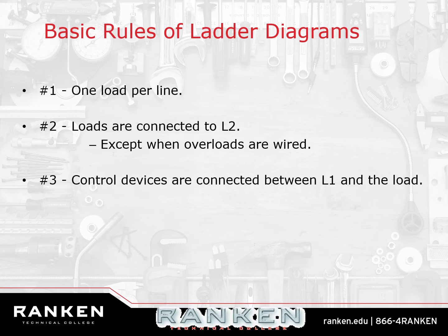Number 4 is all lines have to be numbered, which I have a little bit of a problem with, because there is a difference between a line and a rung, and we're going to talk about the difference between line and rung here in a second. But all rungs, I want you to put rungs, all rungs need to be numbered, not necessarily lines. Okay? This said each line, but I like the word rung better.